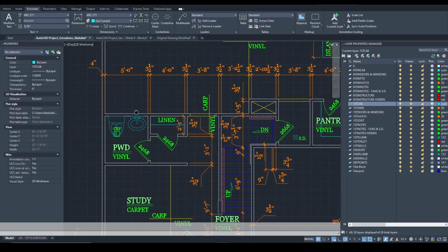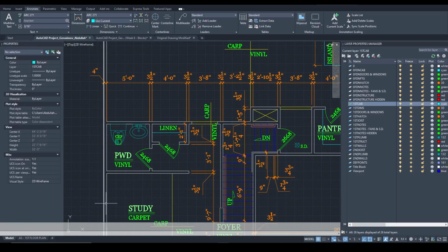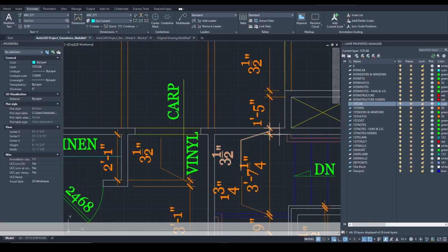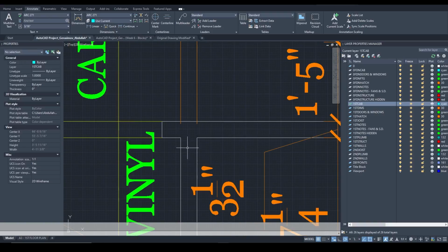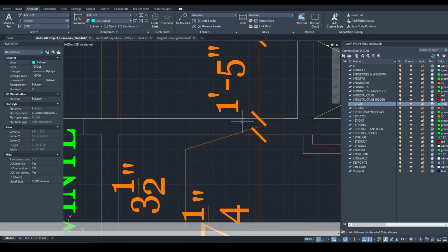And let's start creating a hatch for the interior and exterior walls. The way it's done in the best fashion is simply by hiding temporarily everything that's not related to that, so that anytime there is an interference, there is a line crossing through our interior and exterior walls, we're not going to have an issue.